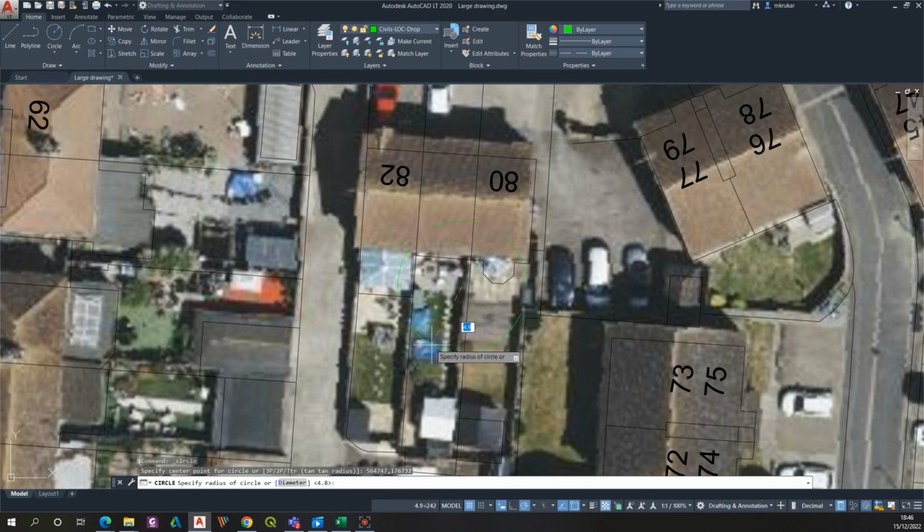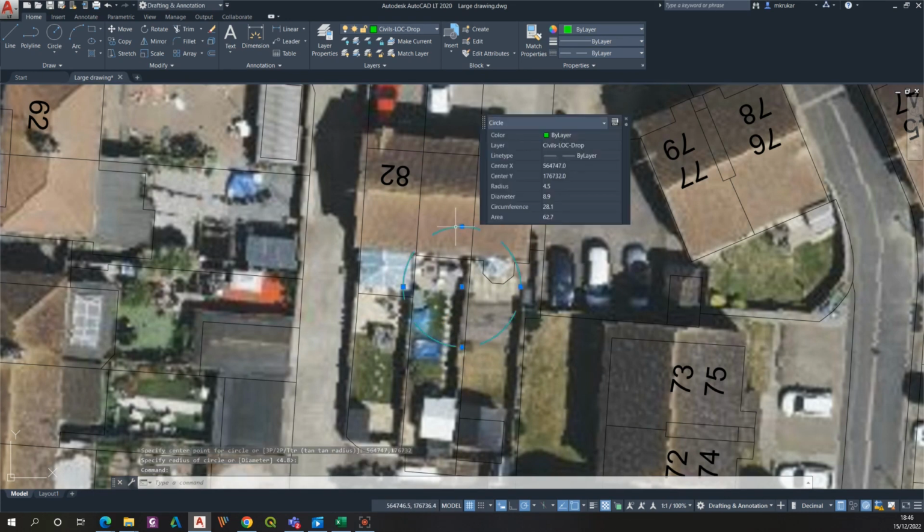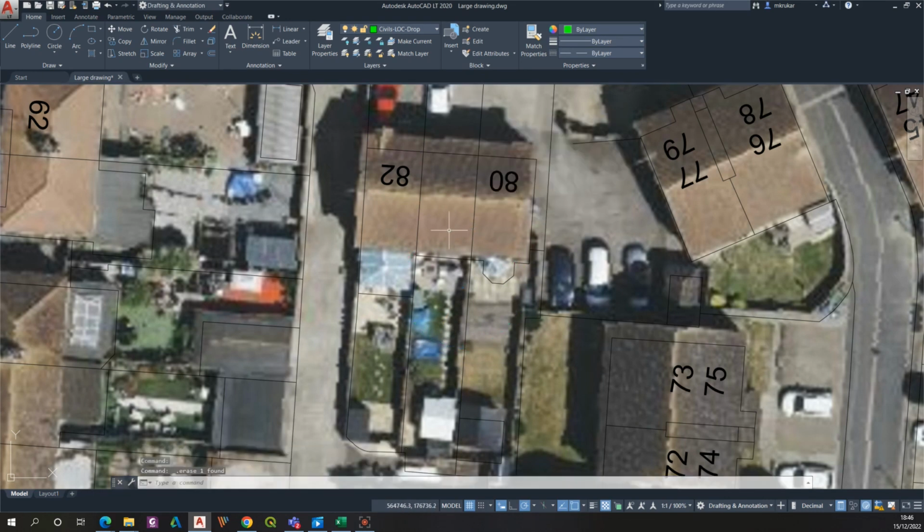The circle has been created, in which the very center indicates roughly the point for the given coordinates. So if you know where this point exactly is, you can remove your circle. So this is how zoom by coordinates in AutoCAD works, or search by coordinates, whatever you call it.